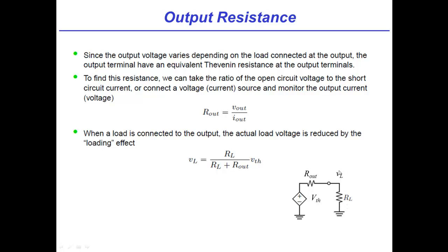And that is going to be different from the internal voltage that the amplifier is producing as part of its amplification. So if the amplifier is, say, producing 5 volts at the output, or trying to, what the load is actually going to see is voltage division. So again, you see the same concept Vivek was fleshing out before, but in the context of the internal output resistance of the amplifier versus the load resistance. The internal source voltage is divided by Rout plus RL, times RL, to give VL.